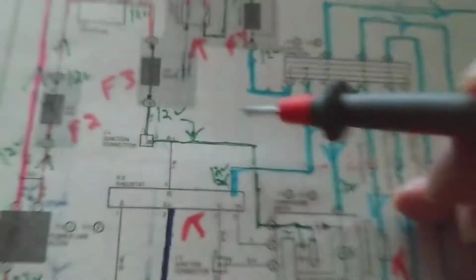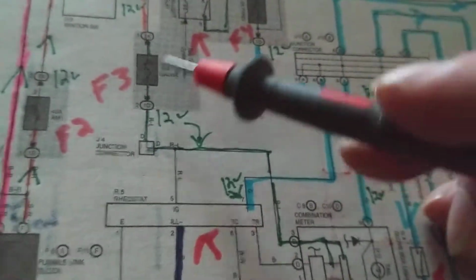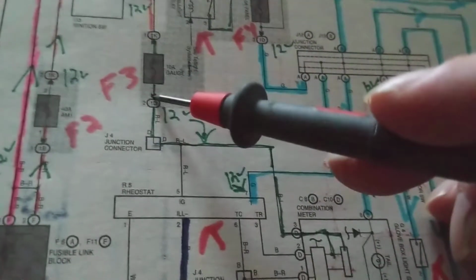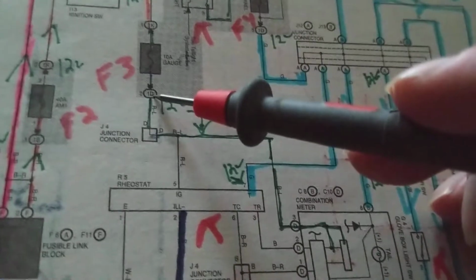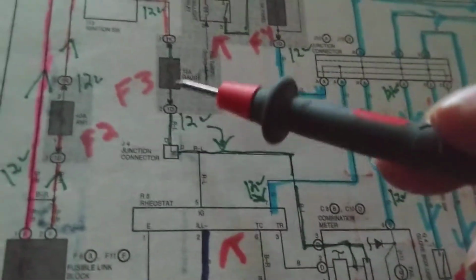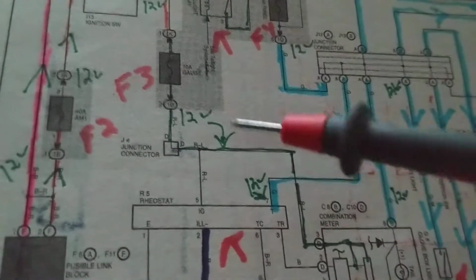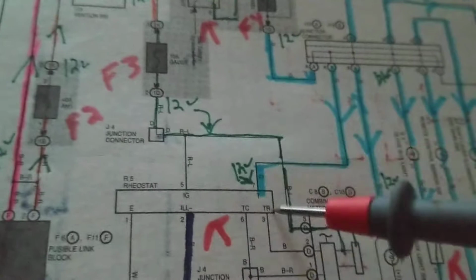Now, what's the other alternative? Before you keep on putting fuses in and blowing them, take an ohm meter. Measure from here to ground. If I measure 1 ohm or less, I have a short. Why should I keep on putting in fuses? Correct? Let me take it out and diagnose where the short is.